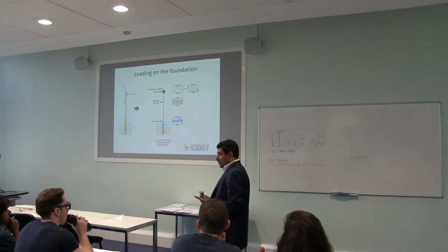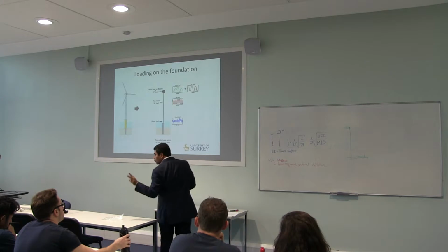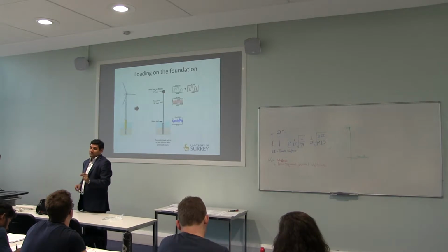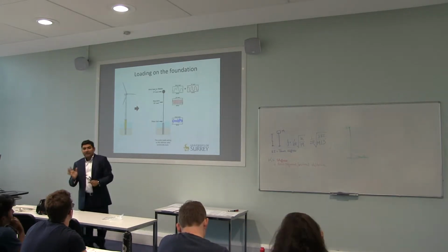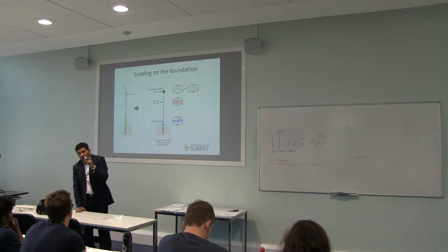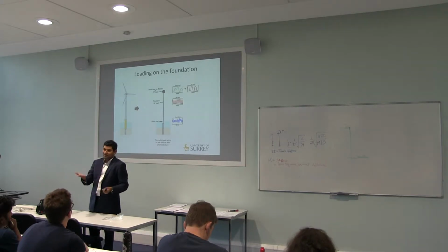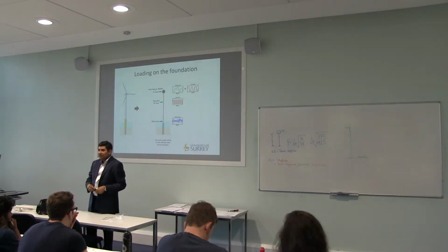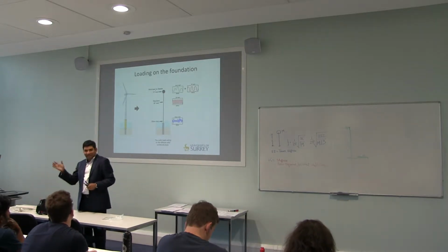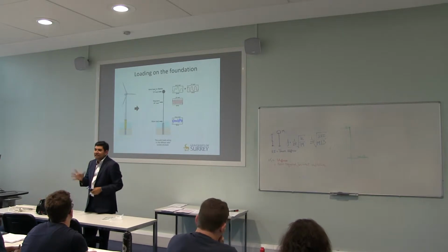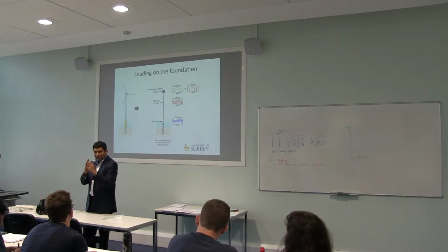Now, for the design purpose, we need two parameters: the wave height and the wave frequency. That means that with different wave heights, you have different loads acting on your foundation, because the more the wave height, the more the load. And wave frequency is how many times per minute it is hitting. Typically you see a 10-second period, so every 10 seconds you get a maximum. But in other parts of the world, they are different.